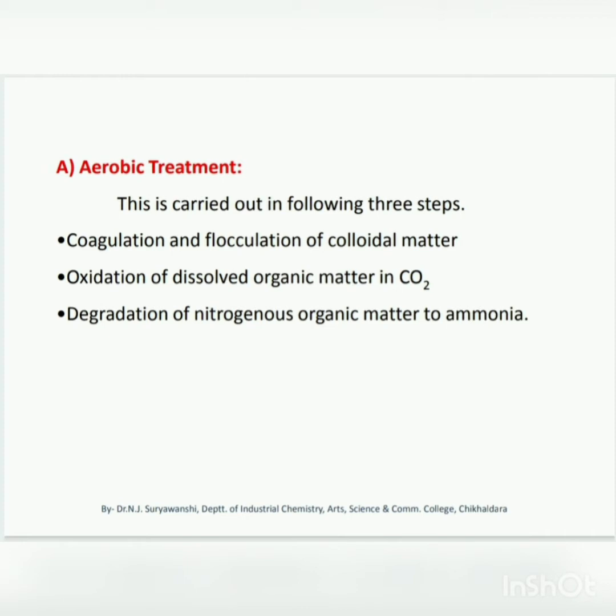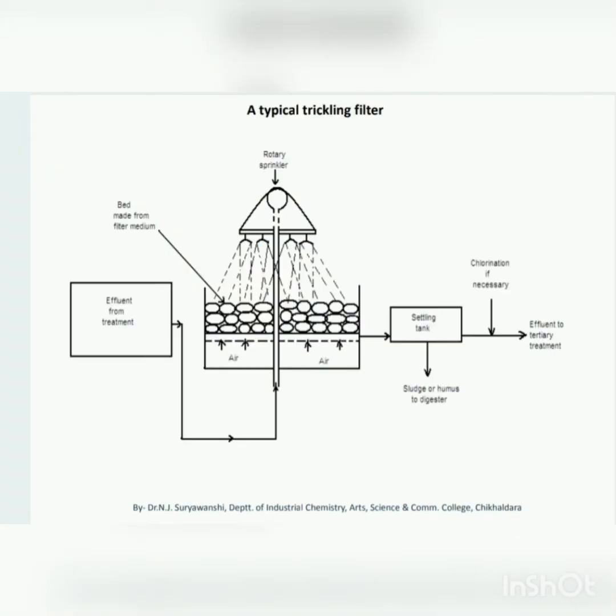It also removes appreciable amounts of oils and phenol. However, secondary treatments are expensive. The most commonly used systems for biological wastewater treatment are trickling filters. The trickling filters consist of circular or rectangular beds which are 1 to 3 meters deep and made of broken stones, PVC, coke, or synthetic resins of size 40 to 150 millimeters.